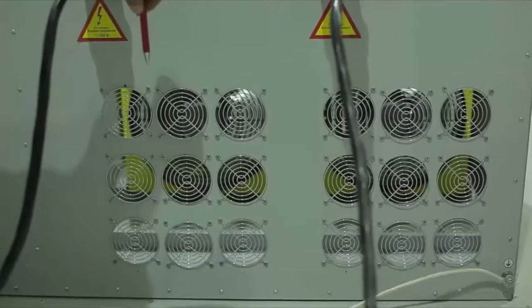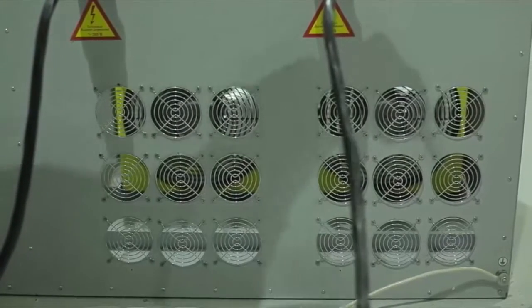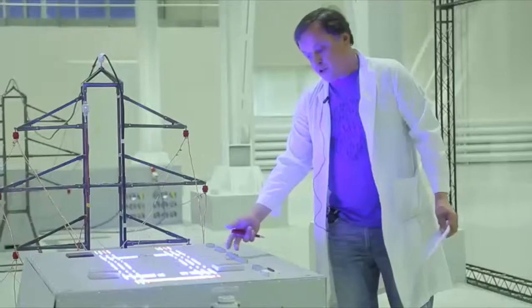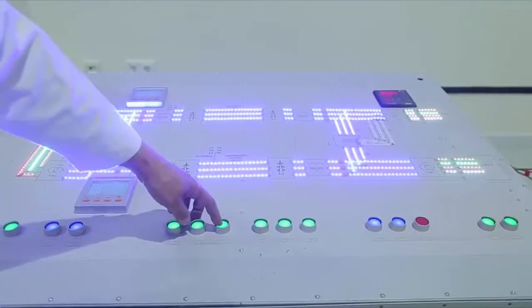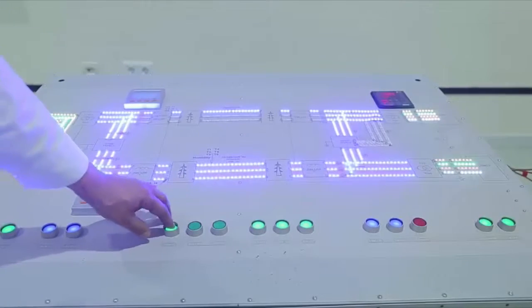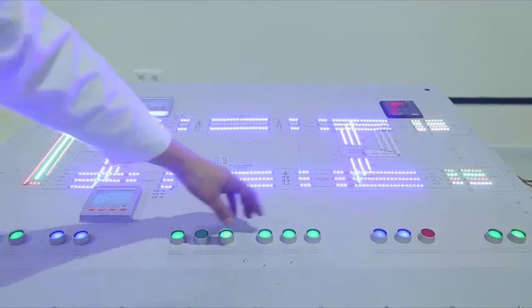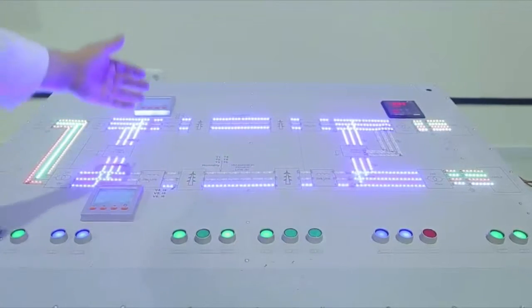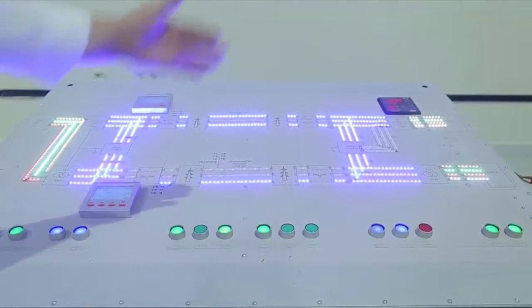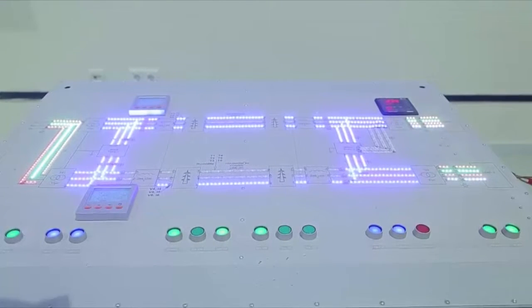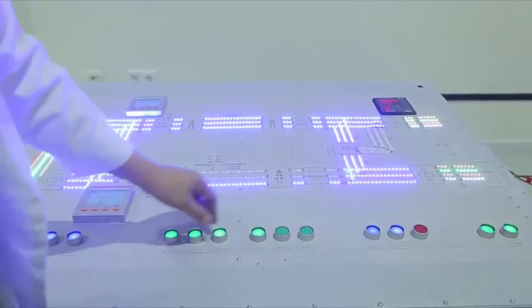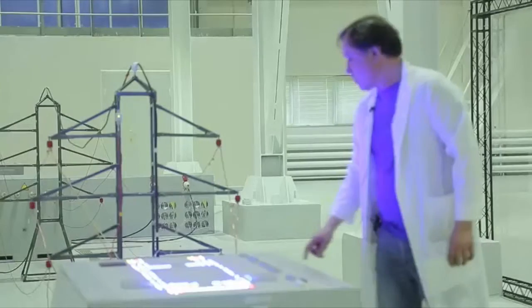As this happens, we observe a new fundamental property of the line, which is that the load continues working. We can keep disconnecting up to 3 phases in the line in any order. The load will continue to be active. These new properties of the power transmission line allow conducting corrective and preventative maintenance without disconnection of consumers.